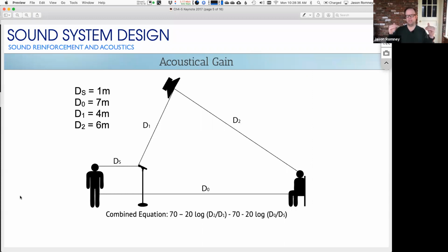Why 6 dB? Because 6 dB is that magic number that you get with the perfect summation. So you want to be at least 6 dB below that point where it starts ringing, so that you don't have any risk of ringing. So here is another version of that equation with that 6 dB safety factor. I'm not going to get into the algebra of why this works, but this is basically what we did.